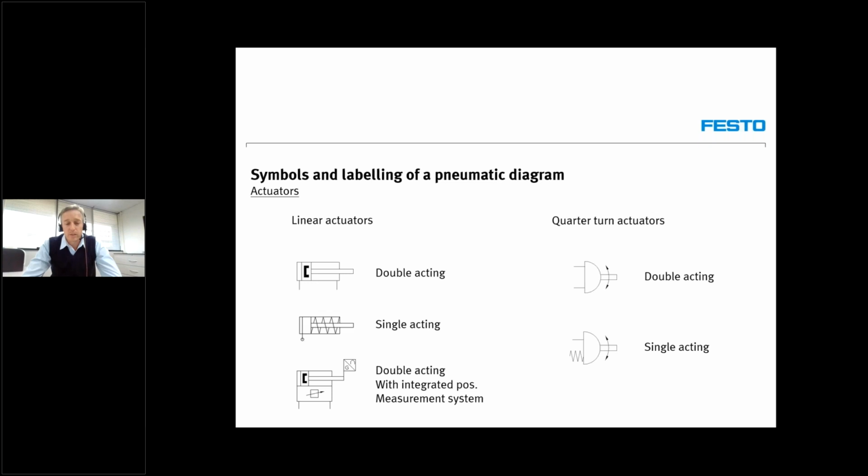So my two suggestions are having an instrument air line or adding an additional filter before the air goes to your solenoid valves, just to take out some of that lubrication. Now, the microfilters do absorb oil particles that are suspended in the air, whereas the 40 and the 5 microns only get rid of the available oil particles. So my suggestion is either use instrument air for your solenoid valves specifically, separately from cylinders if it's possible, or then put in an additional filter.